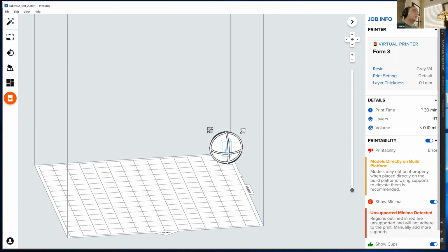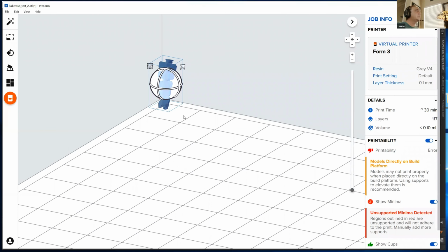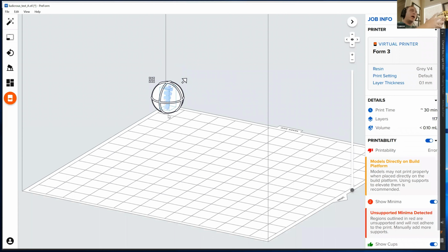Unfortunately, when you're exporting, sometimes because of things that you may have done or going between different programs, and mind you, I went from Maya to my CAD program back into Maya, sometimes it loses sync with what scale is. It's not the end of the world. Scale is actually the easiest thing to fix in 3D printing here. But the interesting thing is, if you look at this, this is a centimeter right here on the Formlabs stage. This is far too small to print. This was supposed to be over a centimeter, okay? But because I exported out of Maya, even though it was the right size in Maya, the STL exporter, because STL is such an old format, just had a really tough time locking onto it.